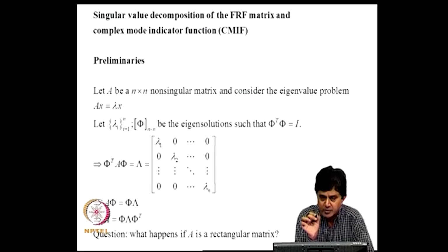Now, FRF matrices in experimental work are often rectangular. What happens if we perform a singular value decomposition of those FRF matrices? What are the quantities that we get? We have seen that for the equations for FRFs, if we use them, there will be a very large number of equations to be solved for the updating system parameters.